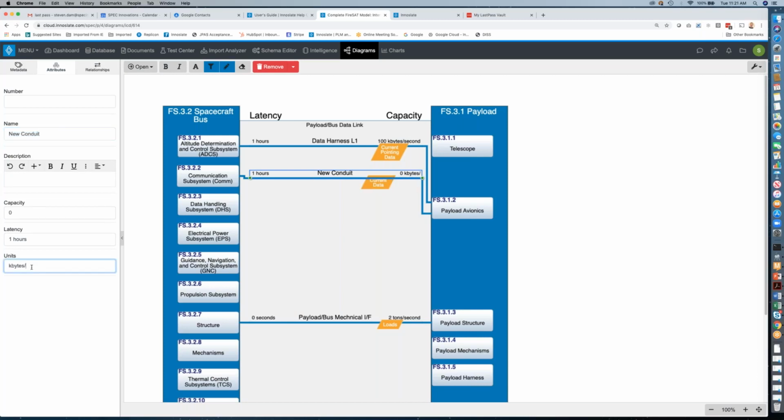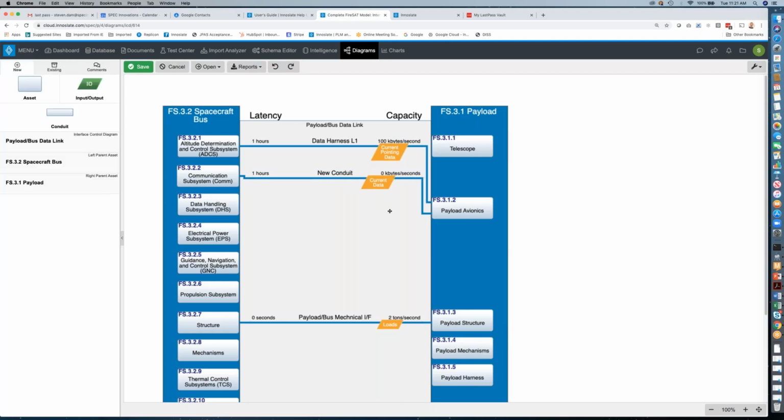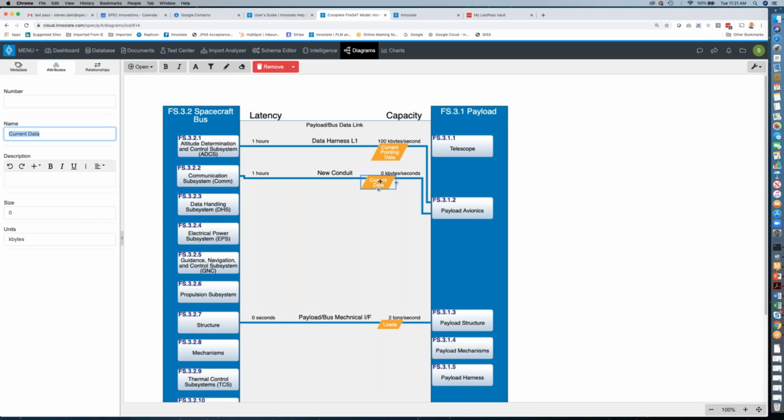I specify a rate with this, and so now it turns gold. So that's something we're going to fix. It's important that these units be correct and consistent, because they are used in the simulator as well. The purpose of checking the units here was to give you a static check before it runs in the simulator, where you'd get an error message.